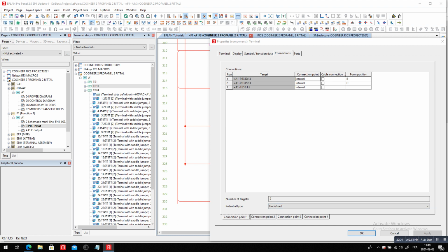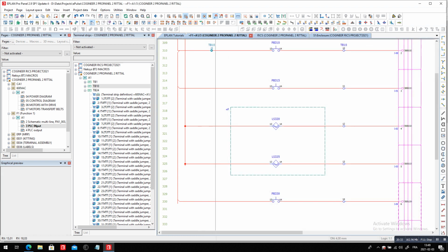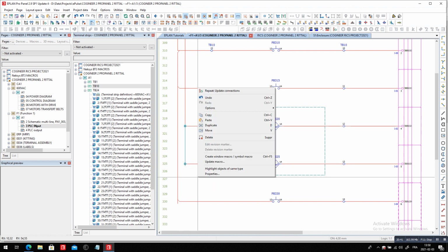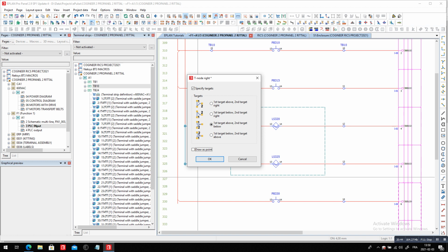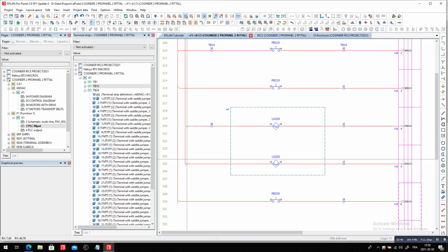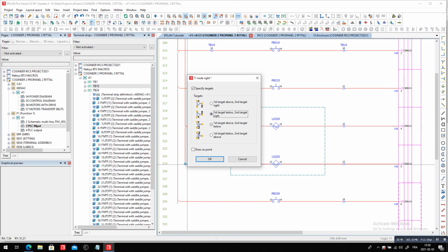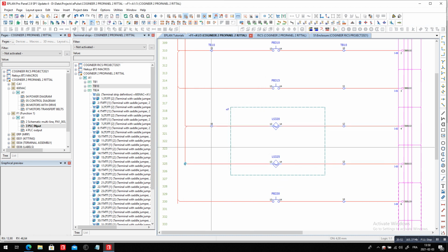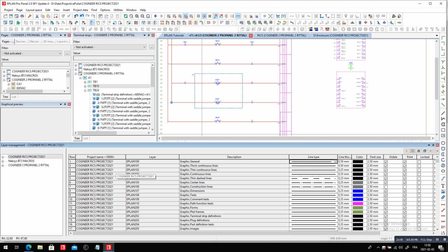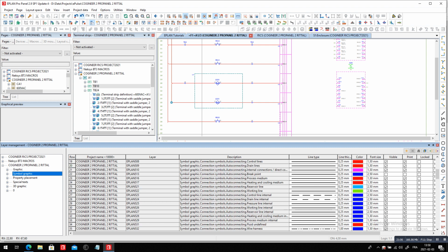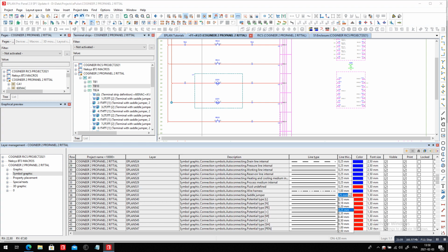So you need another terminal now here, and you actually do the same thing again, with this T node. So instead of having the T nodes not necessarily telling you what it is, take off the dot, and now this goes in here, and this is one of these, because I can go up to 4 connection points, and the others are jumpers. Another interesting thing about EPLAN is jumpers, when they are actually recognized inside your project. So here, this is the project I'm actually working on. You can go on the symbol graphics and you can make the jumper a little bit thicker and even of a different color. So I'm usually using a gray color here.